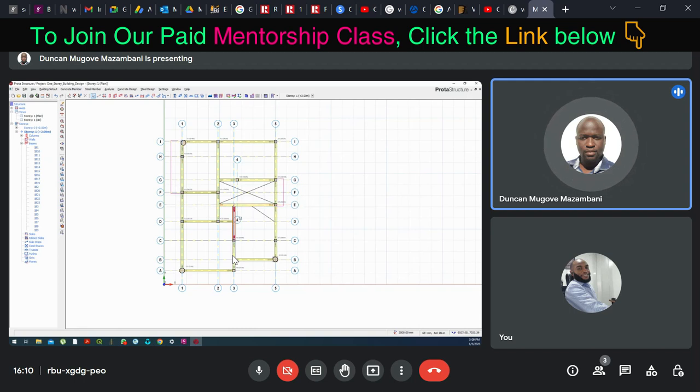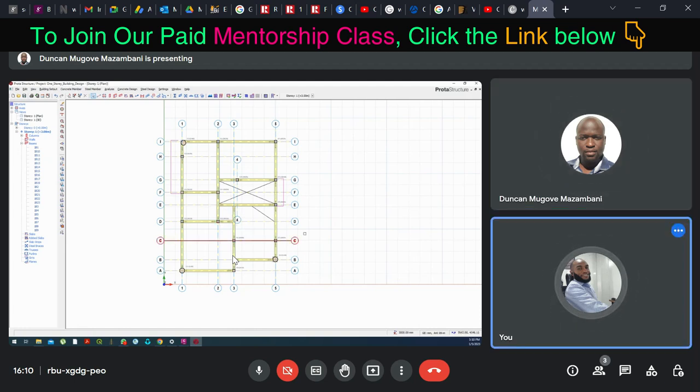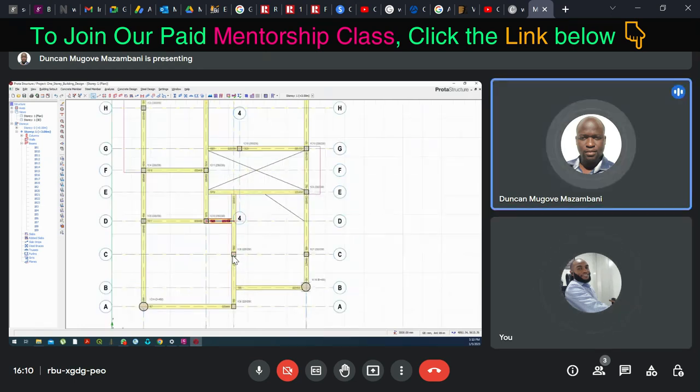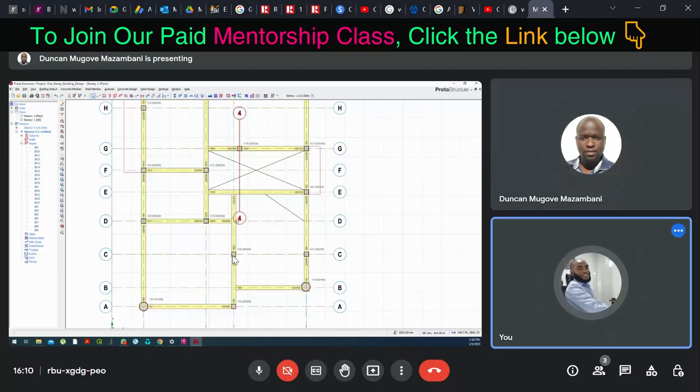These beams here, was it not possible to incorporate this small panel into one of these panels? Okay, that means we need to put a column at this point where you have line 4. That place that you removed that mark, yes, there should be a column there. So I think we should shift this column that is here to that place. Either that one, or maybe move this one that is vertical to exactly there.